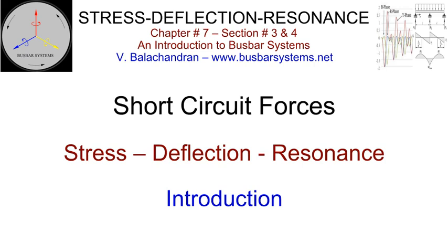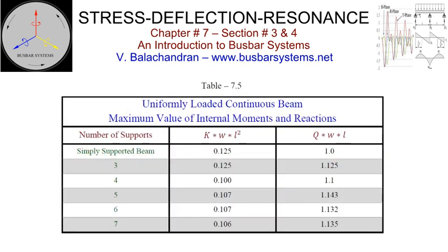It is the normal practice to provide a cushion in the interface between the conductor and insulator, or insulator and supporting member, or both. When the force acts on the conductor, it will yield. Fiber stress must be limited to a value within the yield stress, with a safety margin, to prevent the conductor from experiencing permanent deformation. In a busbar system, the conductor is supported or clamped by many insulators along its length.